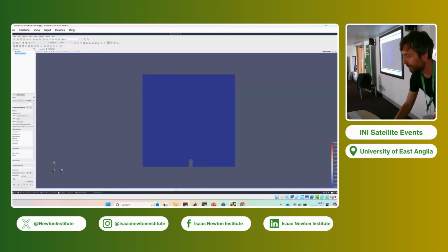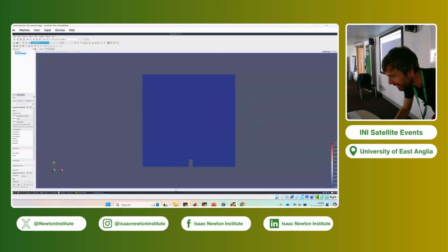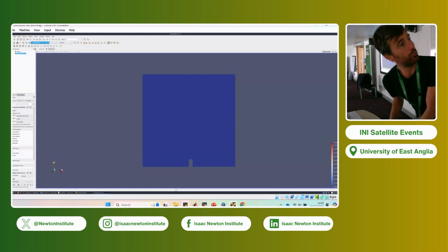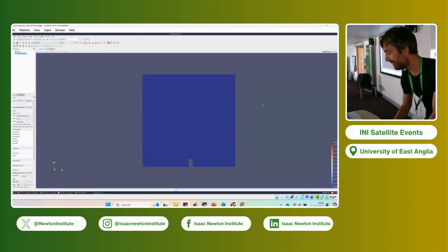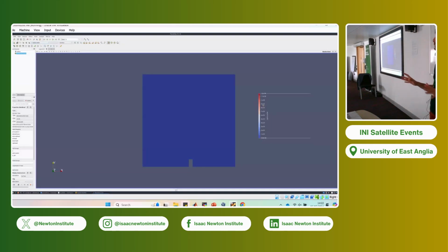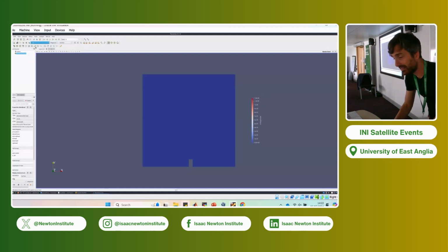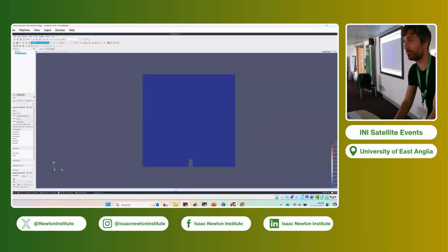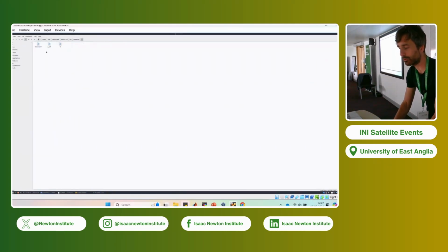This is the alpha field, which is, this is the velocity magnitude. Alpha water is blue. You cannot see the number, but I tell you that this is 0 everywhere, because that's the boundary condition we have input. That's the initial condition we have input. We haven't run setFields yet. So alpha.water is 0. U is 0 because we set initial velocity 0 everywhere. Pressure is also 0 everywhere. Here, ParaView is simply reading within your 0 folder, looking at all the alpha.water, p_rgh, and U.